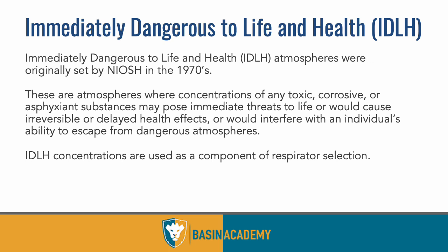IDLH. I mentioned this before. IDLH is not an arbitrary number, but it's a number along a range of a toxin from 0 to 100%, where exposure at that level will cause permanent, irreversible damage to some extent to your body. Whether it damages a little bit of tissue, burns out some nerve endings in your nose, or scars your lungs a little bit, there's permanent, irreversible damage at the IDLH level.